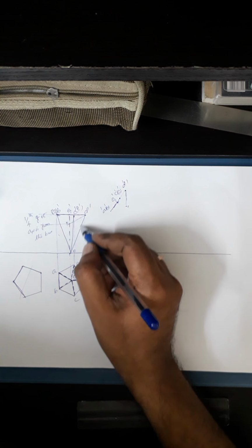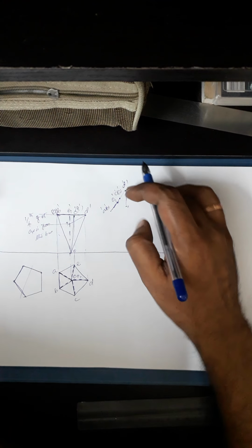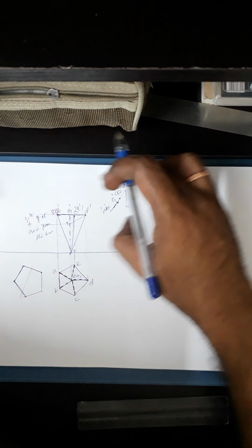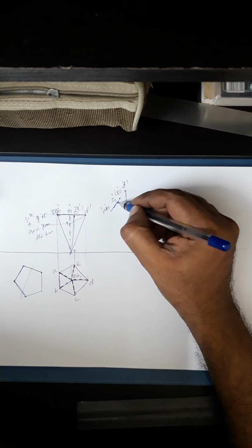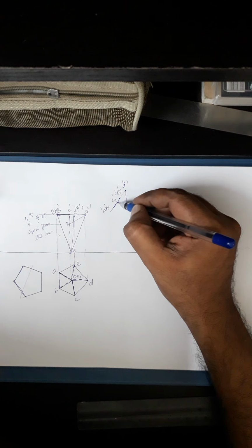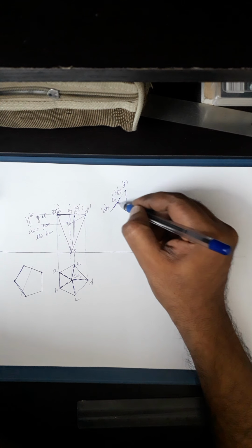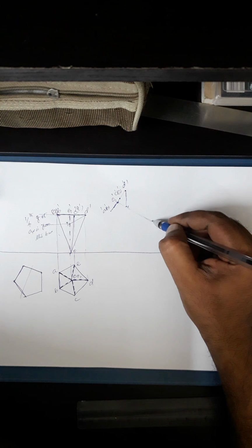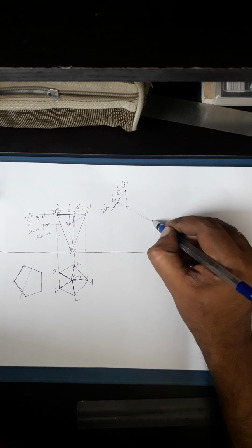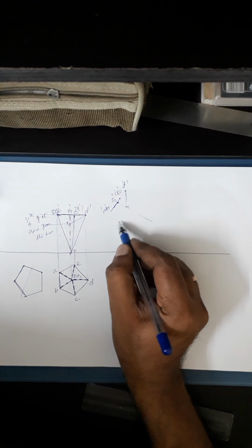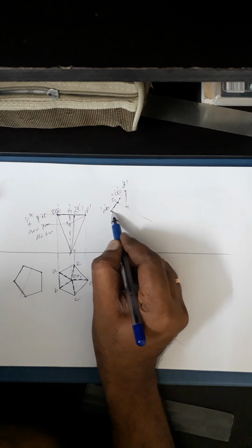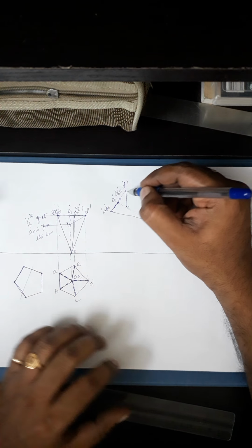So now we can go for constructing this triangle. I know this length, draw an arc, take this length and draw an arc. Otherwise, on this extension you can just go, because this will now be 15 mm. Same thing, I have taken out this 15 mm, extend that length by 60, so this is 15 plus 45. Then I can join like this also. I can draw in any way.